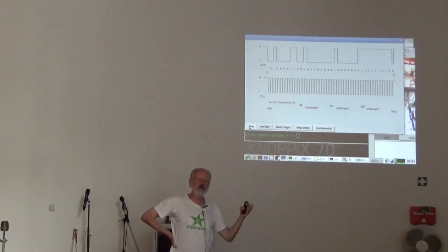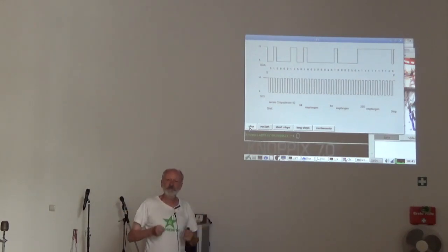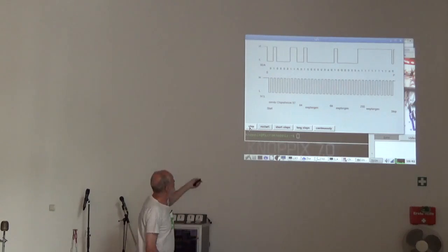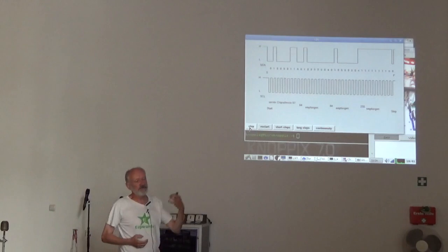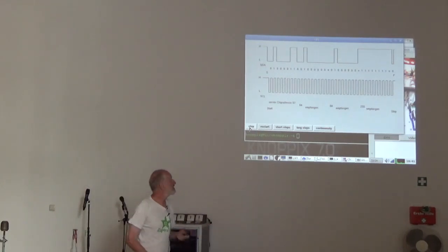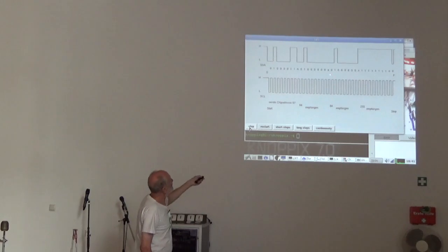I sent before the 64, and it is now in the register of this chip. And when I read it, I also receive the 64. When the master receives a byte, it has to send an acknowledge itself and pull down the 8th bit.